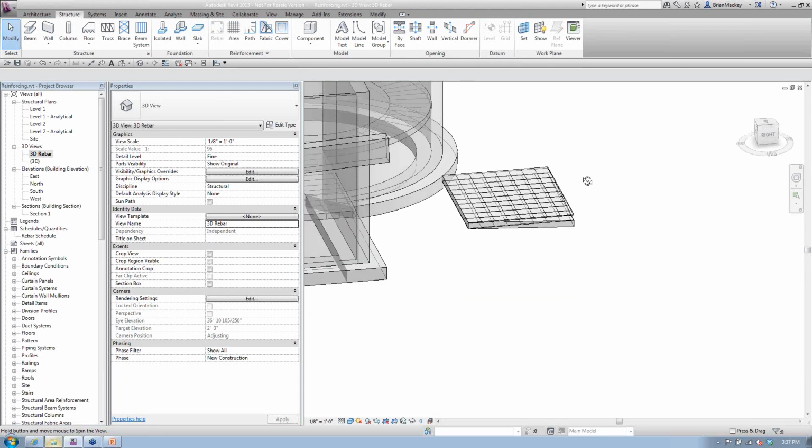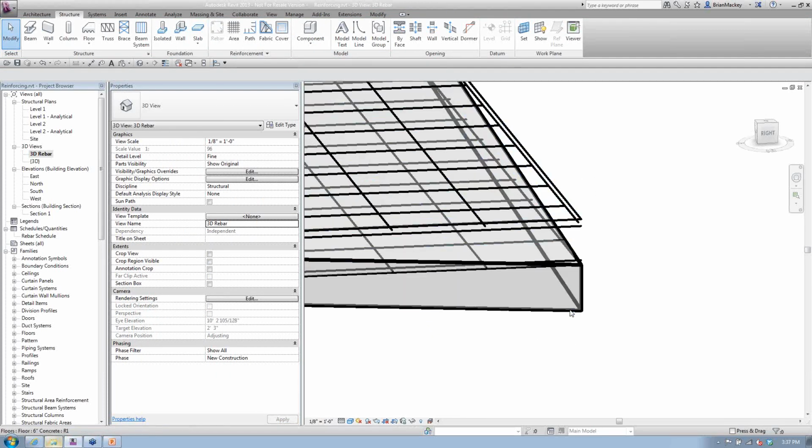But when you rotate it to 3D, it doesn't understand the warping values. So three-dimensional rebar really doesn't work when you're using sets inside of an actual object. Also, it doesn't work too well if you're trying to just place a shape. It's not going to understand that I need to follow the warping surface. I just go off of the work plane of that surface and I call it good.